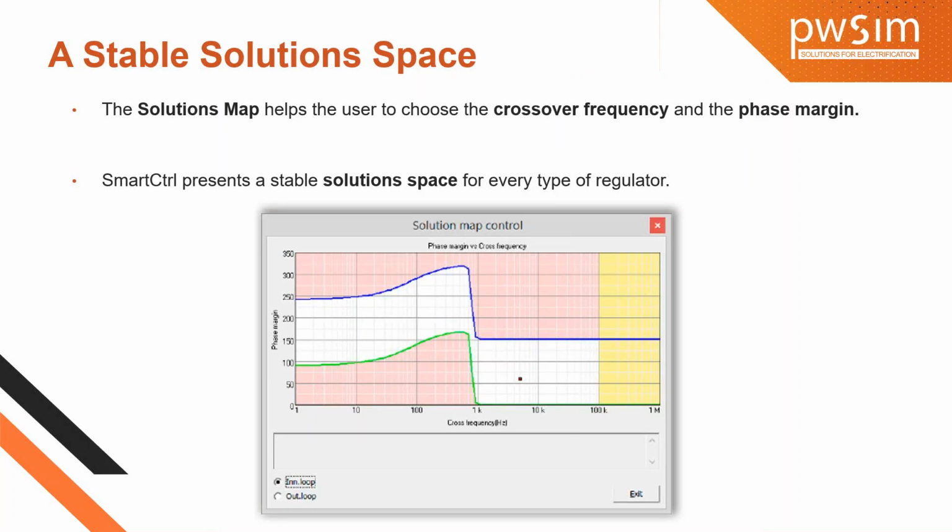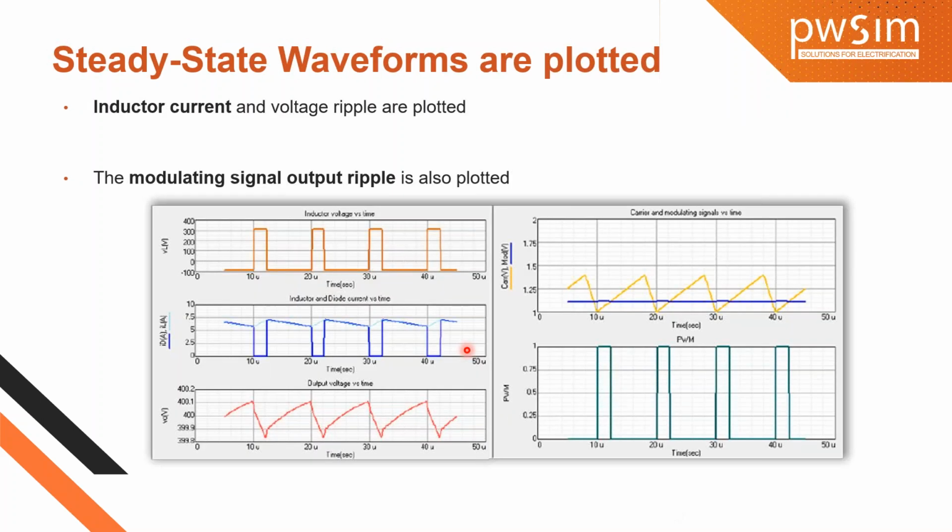So this is the solution map. In this part, you can see, let me take my pointer over here. Here you can see this is my phase margin, gain margin, and phase margin versus crossover frequency, which I marked as a point. Once I want to change something for the stability analysis, I can change this point, which will be updated in real time. All these values you can visualize in real time: the poles and zeros, the Nyquist plot, the Bode plot, and the time response.